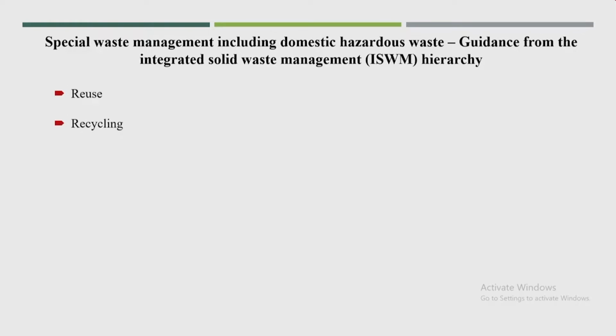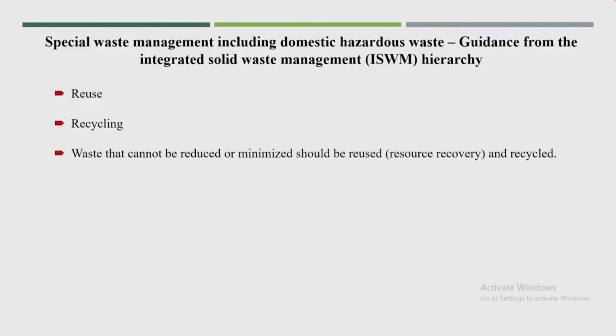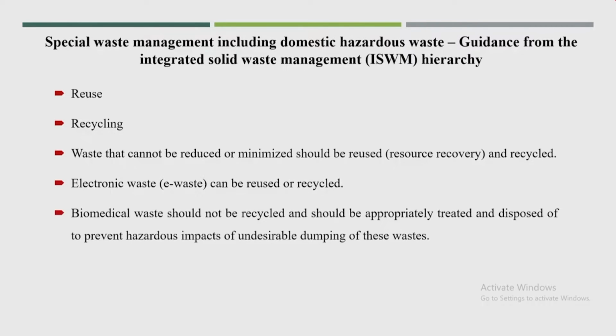So, for special waste management including domestic hazardous waste, the guidelines follow the integrated solid waste management hierarchy: reduce, reuse, recycle, and waste that cannot be reduced or minimized should go to reuse or resource recovery. E-waste can be reused or recycled. Biomedical waste should not be recycled and should be appropriately treated and disposed of to prevent the hazardous impact of dumping such waste. Mostly biomedical waste goes to incineration facilities, and only a very small amount gets recycled, and that is only the plastic coming from biomedical facilities.